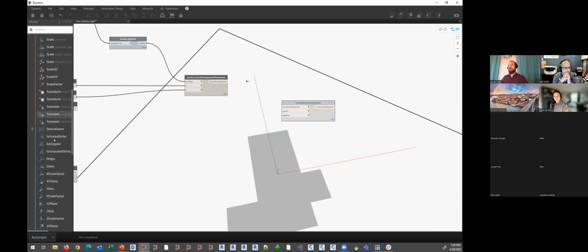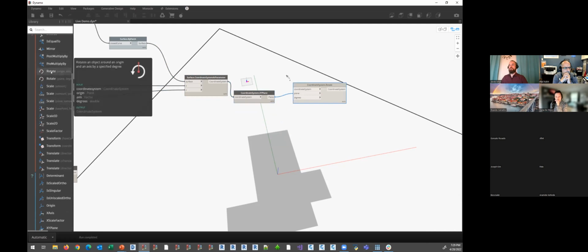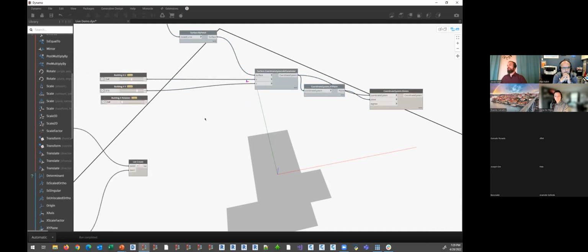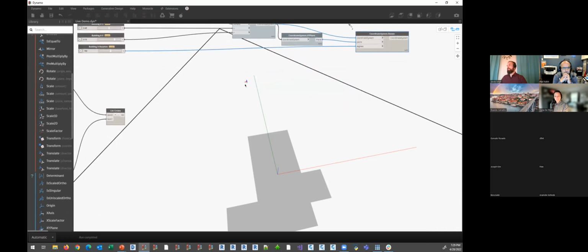The reason I go with plane is because I can quickly pull the XY plane from another coordinate system. And then I don't have to worry about the other rotation option, which requires an origin and an axis. That's 2 hits in my memory. I want to just have 1. So we can put that in there, hide all this geometry preview, bring my rotation parameter over. And now I can adjust this value. And hey, look at that. That coordinate system is rotating as I click it around.